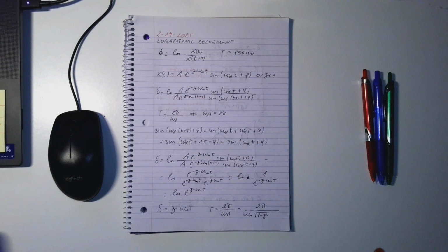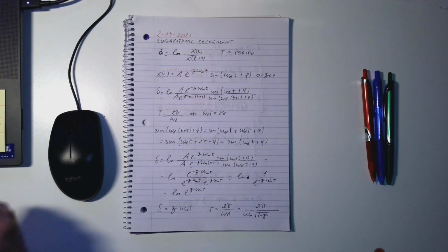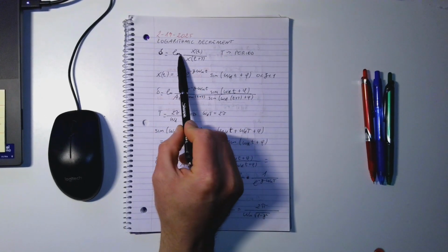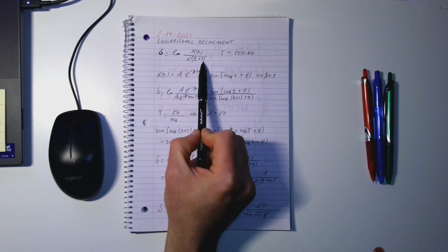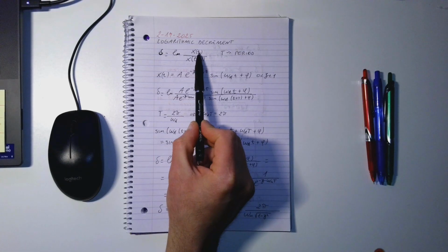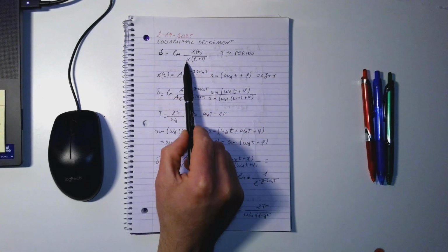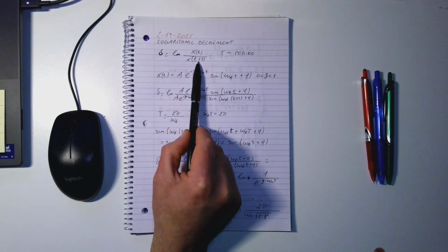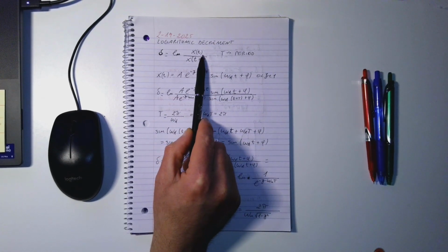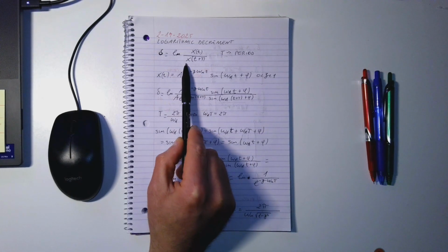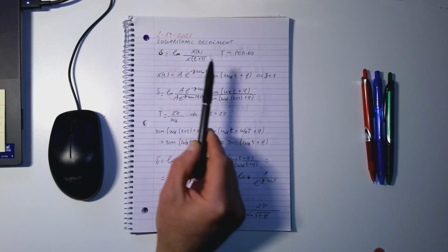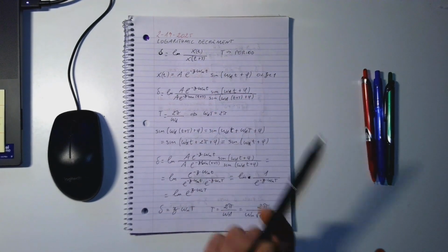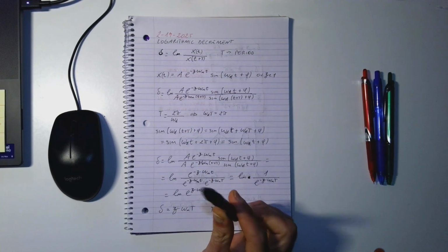We looked at the formal definition of the logarithmic decrement, and we said that it is the natural logarithm of the ratio between two quantities, the amplitude at a certain time and the amplitude at one period after that time. So mathematically this is what we write: x of lowercase t divided by x of lowercase t plus uppercase T. Okay, so we started from this definition, and then from this we can determine the properties.